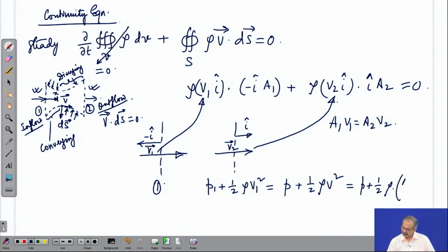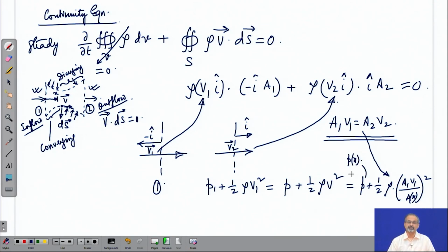and then you try to write that velocity at that section in a way like this, because we have come to know that continuity equation relates the product of areas and velocities like this. So, if you look at this, you have the x location incorporated and you can also mention this as P x because the pressure is changing along the location.